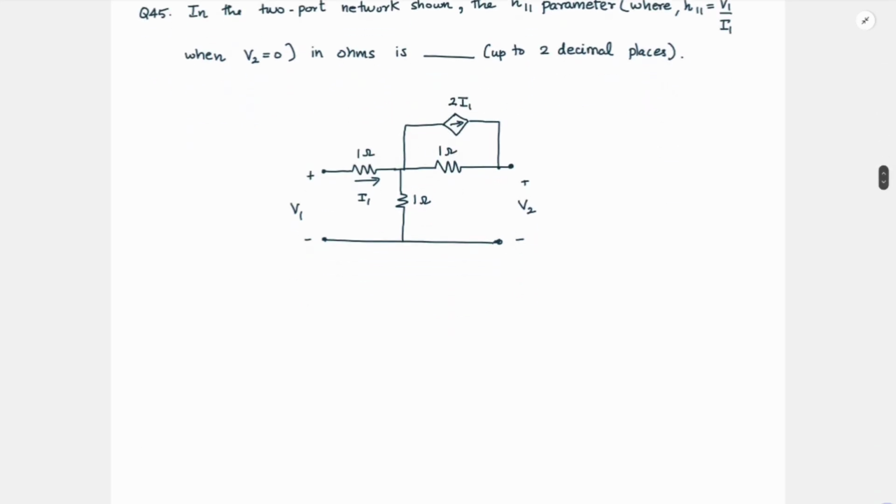So this is the network, two-port network. They have given H11 is V1 by I1 when V2 equal to 0. Just with this we can actually find all the H matrix relations. I can write this as V1 is equal to H11 I1 plus H12 V2. So from this only they have derived this, right? Here anyway it should be H12. So from this, what can you get?